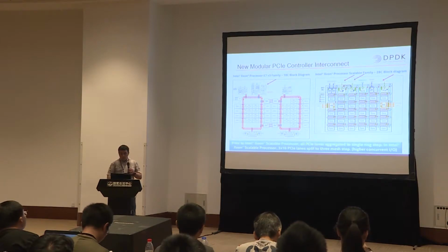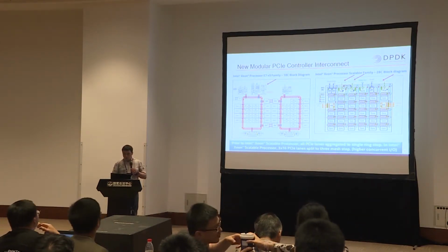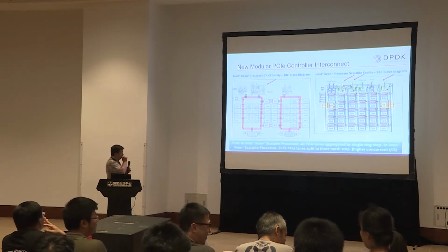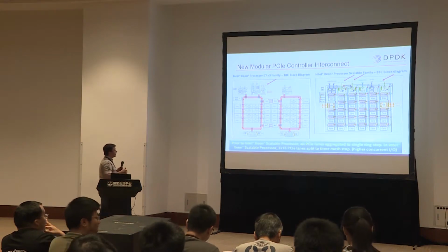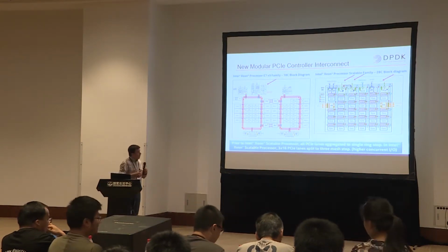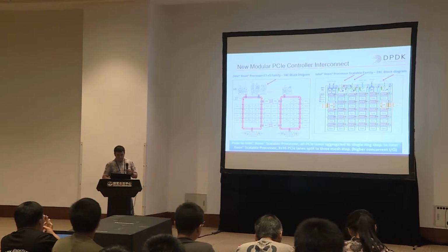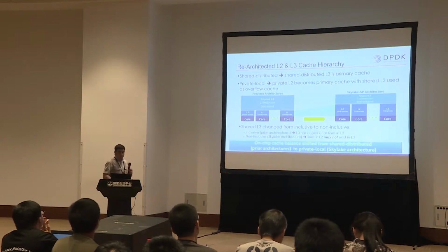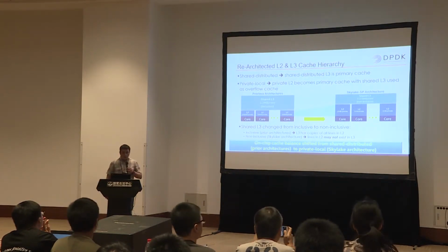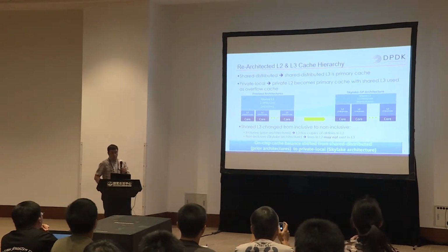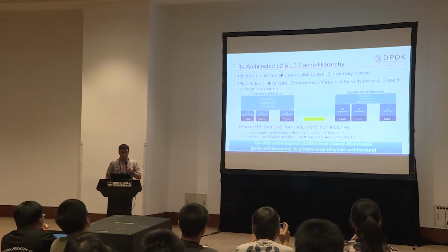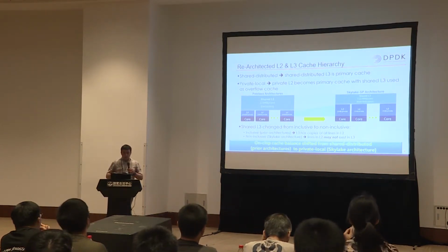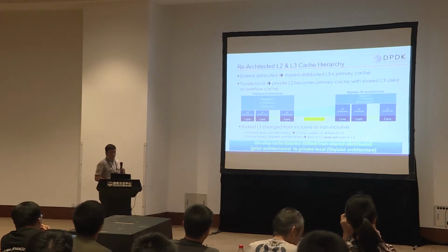So Skylake moved away from the unified architecture to a split model architecture, which in turn increases aggregated traffic and reduces architecture conflict. Another big change relates to cache hierarchy. Both size and properties of L2 and the last level cache have changed in Skylake. And it's important to understand those changes to get the best performance out of the Xeon Scalable platform family.